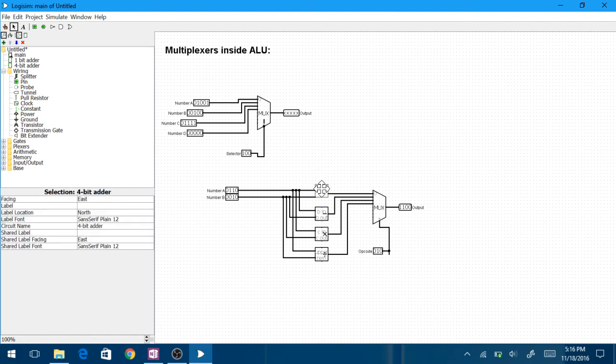So we just drag this into place. Now we can start using our own adder chip. Remember our opcode for our ALU, that was 000 for addition. So I'll go ahead and adjust the ALU so that we're doing addition here. And then remember that in order to get our adder to work, we always have to carry in a 0 to get it started. So we still need this static 0 coming in to get the ALU started. And then once we've got that going, we can perform addition.